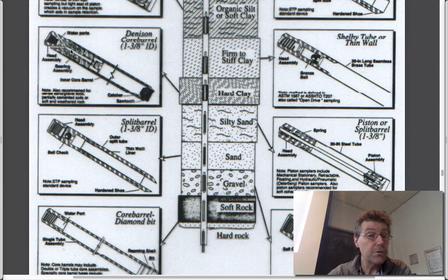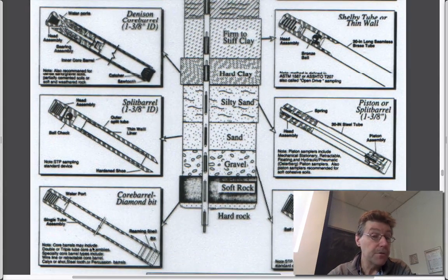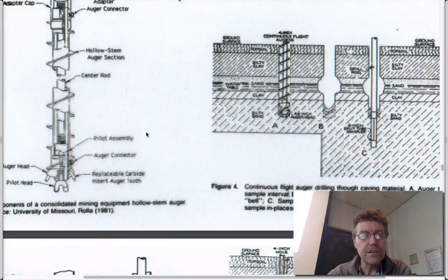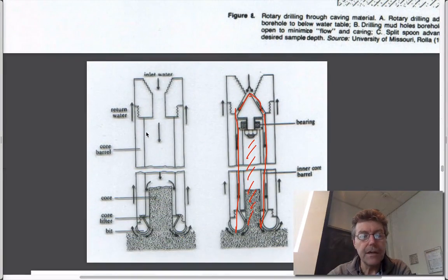And rock core, which you can get by a regular core barrel, which you get by diamond drilling, either with a single wall or a much nicer, I'm not sure that is a multiple core drill barrel, which takes on this idea of the advantage of being able to keep the core away from the drilling fluid. In this case, the drilling fluid only sees it right here and then flushes back around the top again. And so in terms of contaminating the fluids, not so much.